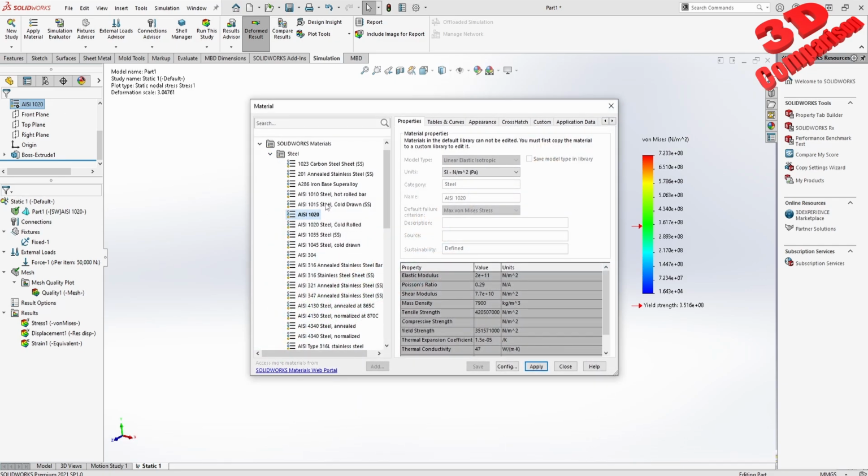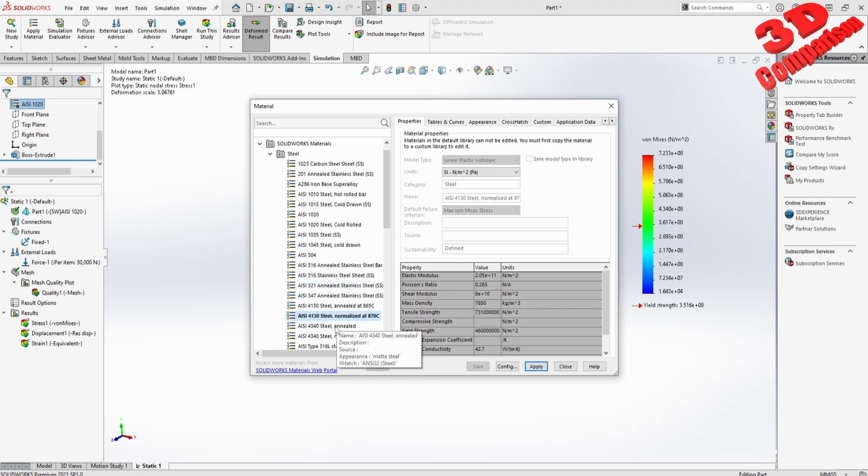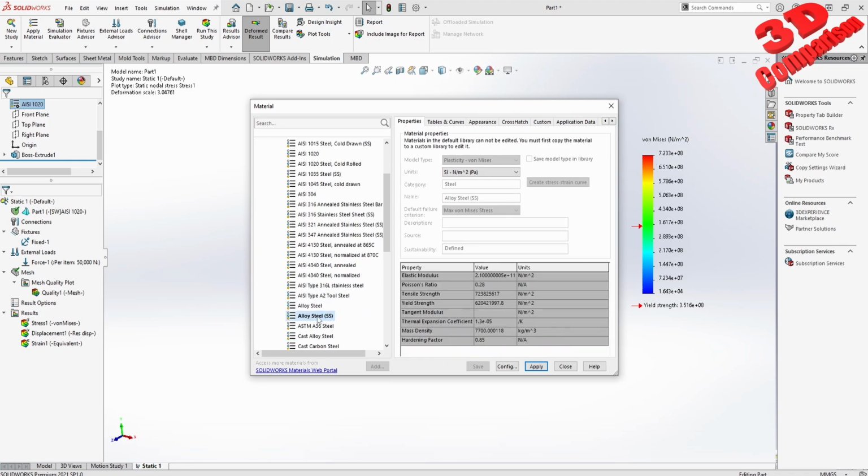So just for steel, we're going to see all of those materials. If I, for example, change this, we're going to see that this will only have a yield strength of 282 megapascals. But as we can see, some of those will go beyond that. So depending on the material that is selected, we can go for larger values over here.